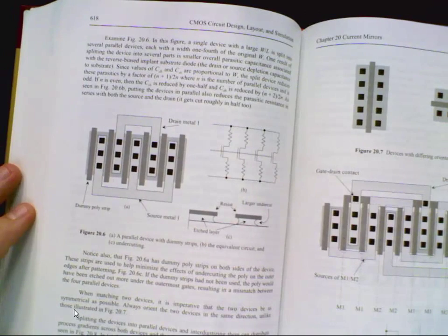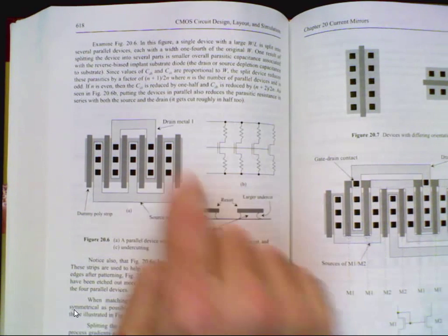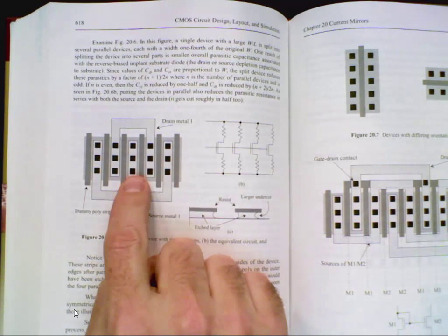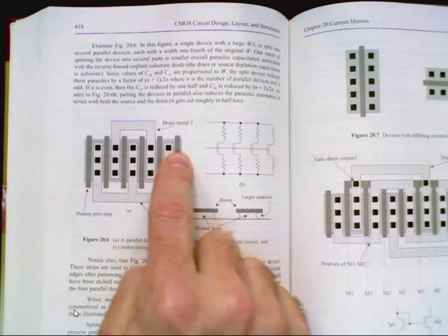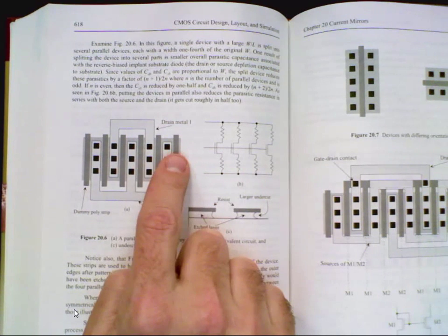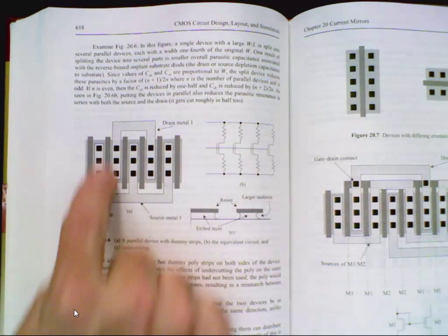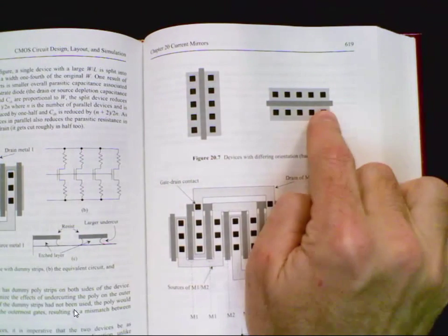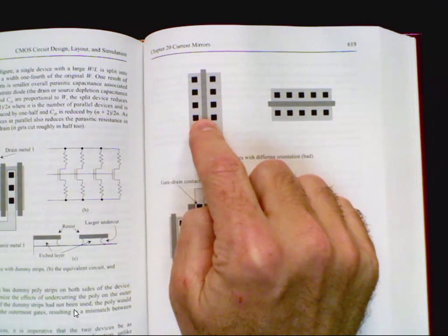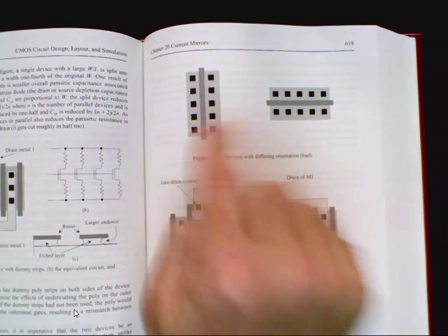The other thing is, it's possible to lay the transistors out in parallel. What you want to do when you're doing analog designs is, the transistors, which these things right here in the middle are, you want to try to have the same adjacent structure. So you'll often, and they do this all the time nowadays because of the lithography, put dummy structures that don't do anything. They're just there to ensure that this transistor and this transistor see the same adjacent structure. Another thing that's important is orientation. If you're trying to get good matching, you don't lay out one transistor that's horizontal and the other one that's vertical.